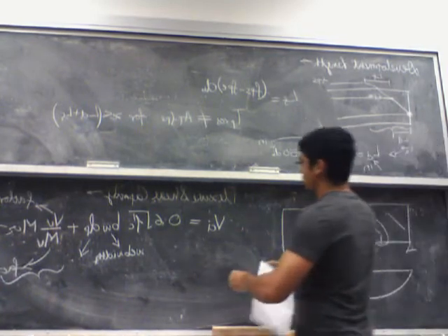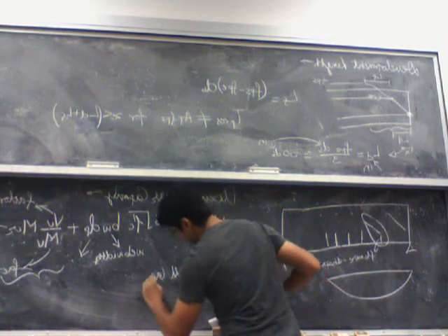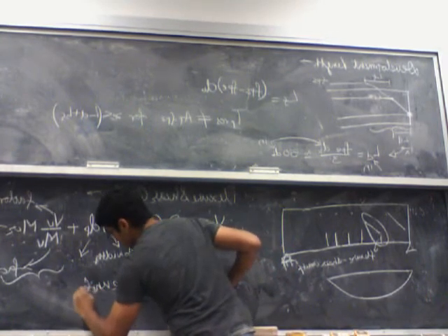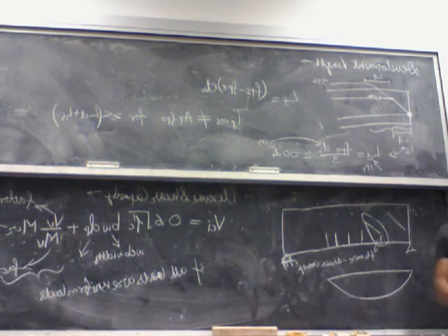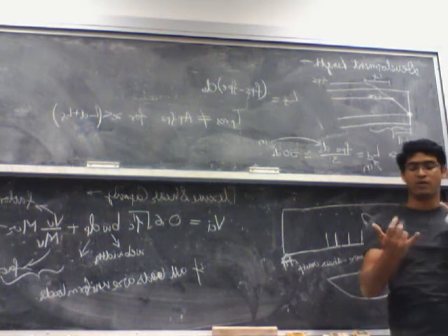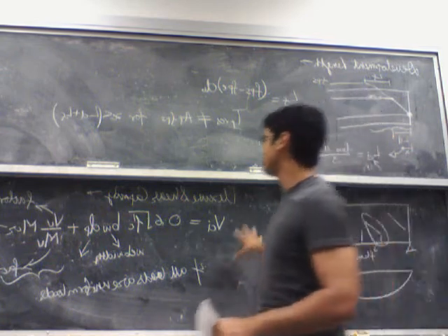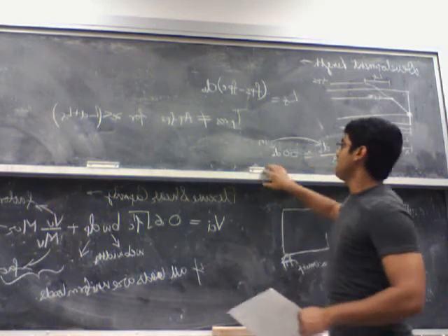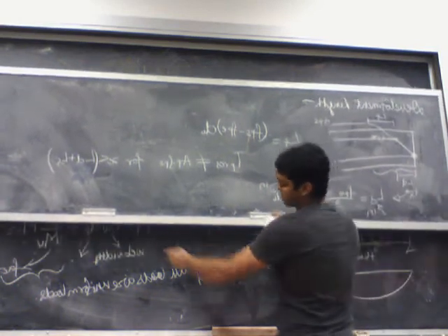And this formula is only applicable if all loads are uniform loads. So if all the loads, that means your self weight is always a uniform load, your dead load and your live load, if all of them are uniform loads, you can use this formula to calculate the value of V_ci. Now if my dead load or my live load is not a uniform load, there is a slight variation to that formula.